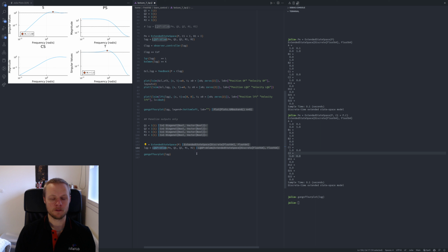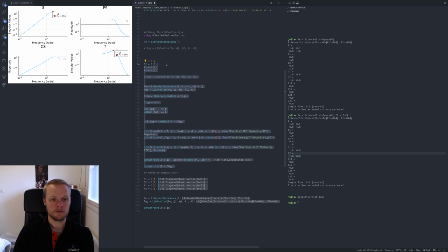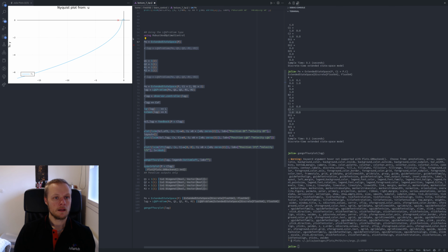So that's of course not a particularly interesting controller, and that's also why we get some phase loss compared to before, and we see a much worse sensitivity function here. We can actually look at, for instance, the Nyquist plot. Let's see if I can spell. And we can do that using this loop transfer function that we had from before. Let's see if I recreate this thing. That gives me, maybe that's a bit hard to read.